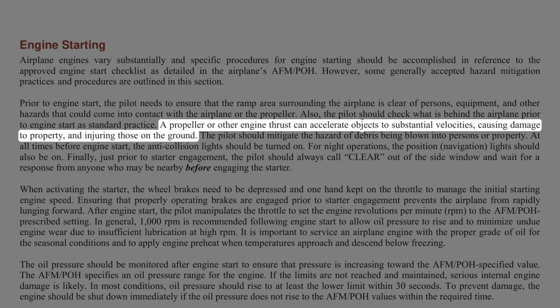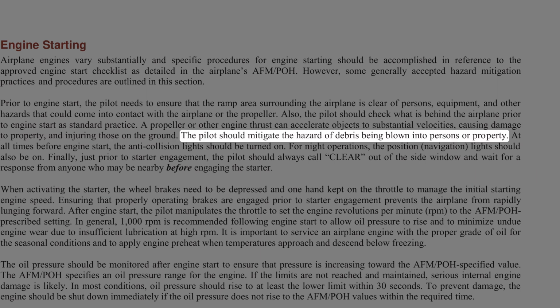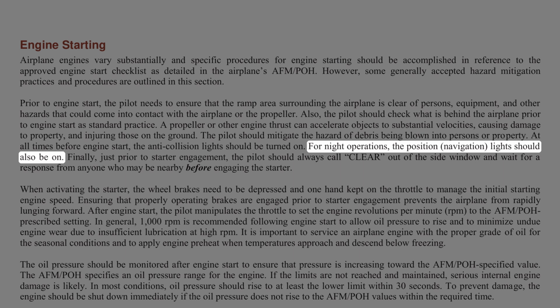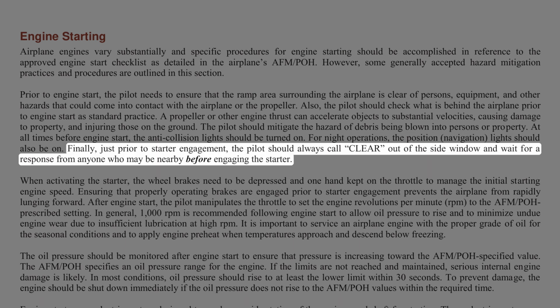A propeller or other engine thrust can accelerate objects to substantial velocities, causing damage to property and injuring those on the ground. The pilot should mitigate the hazard of debris being blown into persons or property. At all times before engine start, the anti-collision lights should be turned on. For night operations, the position, navigation lights should also be on. Finally, just prior to starter engagement, the pilot should always call "clear" out of the side window and wait for a response from anyone who may be nearby before engaging the starter.